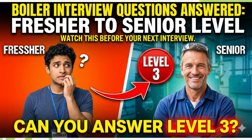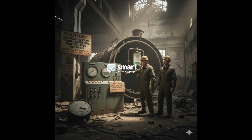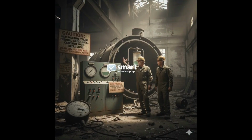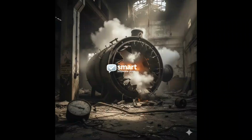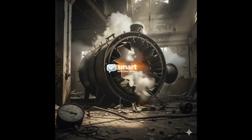Question: What specific points should be observed during boiler inspection? Answer: During boiler inspection, special attention should be paid to the condition of tube, drum, furnace, refractory, valve, gauges, pump, piping, and safety devices, looking for corrosion, cracks, leaks, sealing, or sludge.